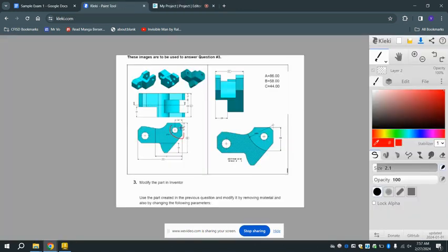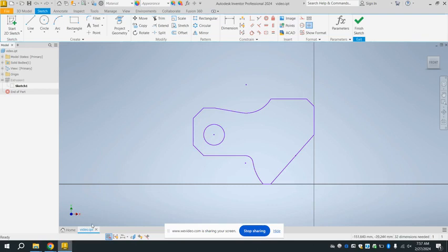First, you can start off by adding in this circle to your drawing. So we're going to start off with that. We're going to go in by 14, and you're going to go down 14. And the diameter of the circle is 11. After we edit this, we can go ahead and delete these just so it's cleaner.